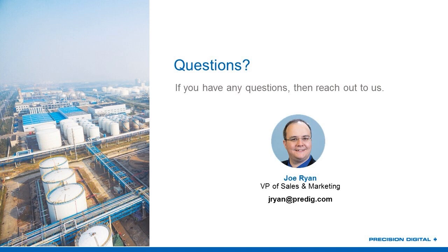What I would suggest you probably do in that case, if you just want a remote display, there's a couple ways you can do it. You could use the 4 to 20 milliamp output and send it to another panel meter somewhere else. In the case of, say, a SuperNova, you would only be able to do that with one of those values because we only have one 4 to 20 milliamp output.